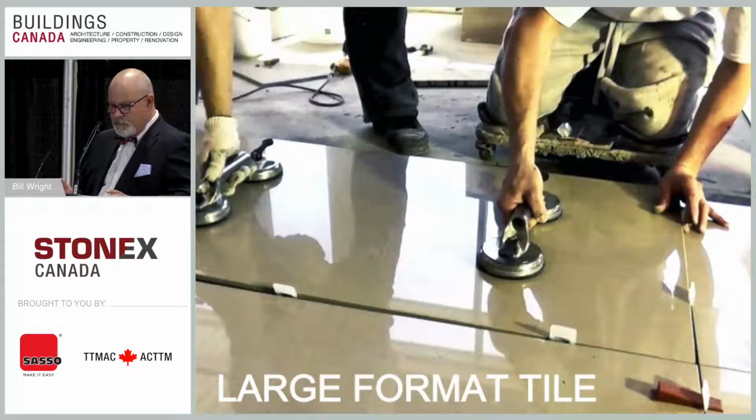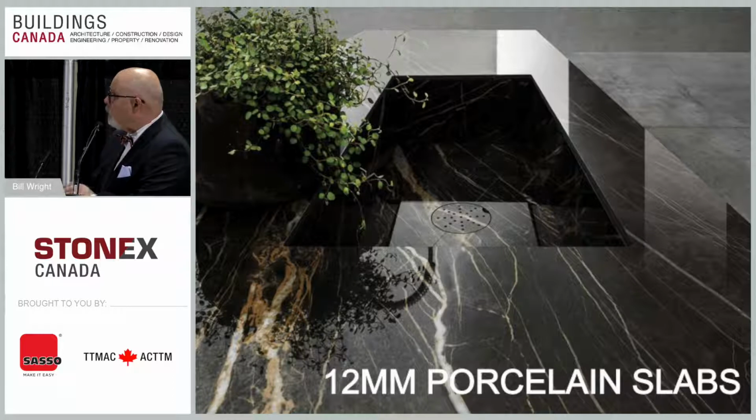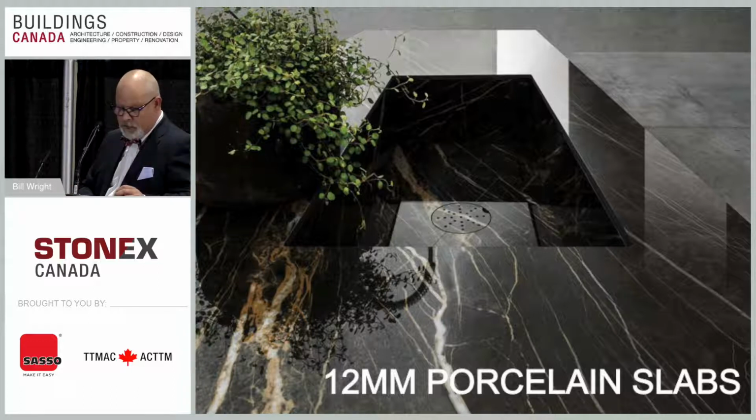Large format tiles, like I said, we're getting into 120 by 120s, 90 by 90s. These require a very, very skilled set of installers to install. They are out there. When we're doing these types of materials, it's important to consider the patterns. We want to try and eliminate wastage. If you need some help on that, most of the manufacturers are more than willing to sit down and show you how to best maximize the size of the pieces that you're using. We're getting even into 12 millimeter porcelain slabs now for countertops, interiors and exteriors. Again, the same practical benefits for porcelain tile in terms of its impact resistance, its scratch resistance, things like that.